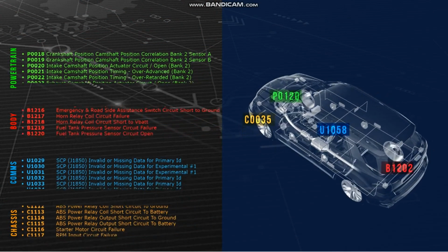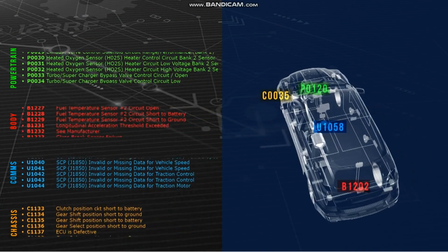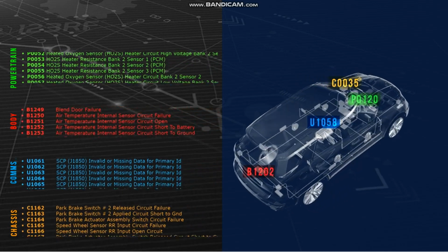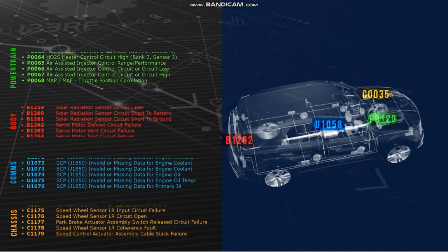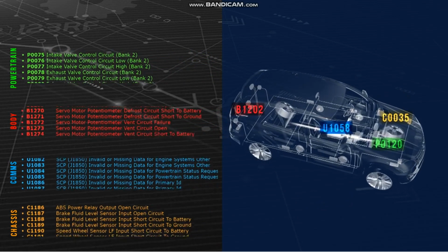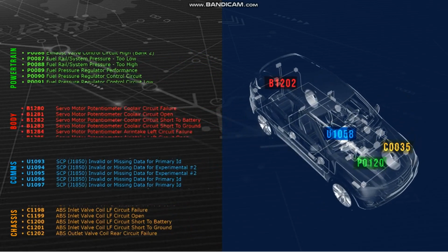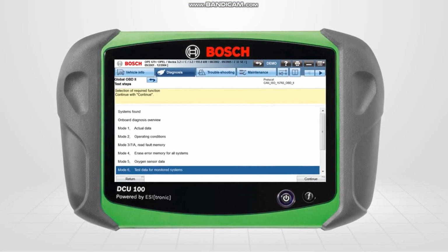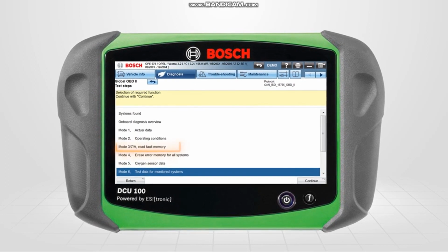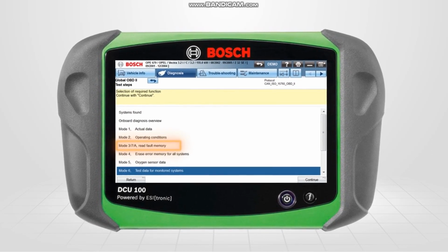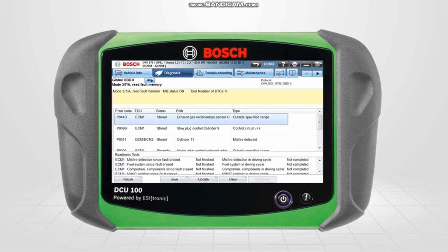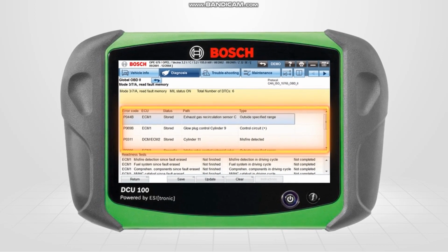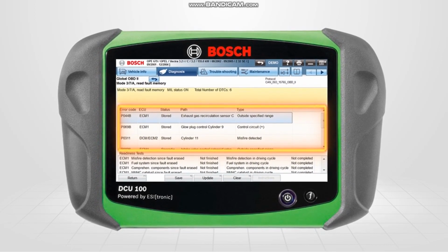Fault code structure is clearly defined under OBD2, which is in accordance with the SAE standards. There is scope within these standards for manufacturers to develop their own specific codes, although these must follow the same structure as the generic SAE-defined codes. Using generic OBD scan tool software, when we navigate to mode 3, 7 or 10, we are presented with a list of diagnostic trouble codes, including a description of each code. The fault codes may be either pending or confirmed, depending on the chosen mode.